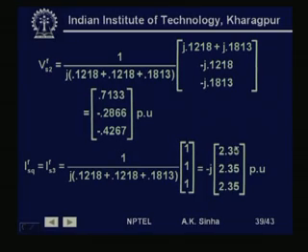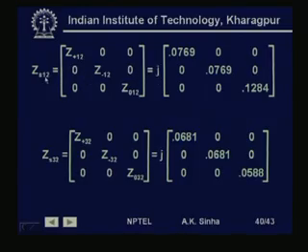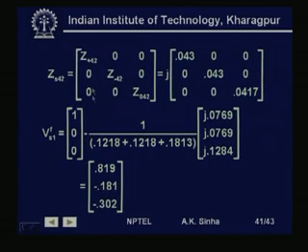So, we have got the values, I am sorry, this should be IFS2. So, this is the value that we will get for the fault current positive, negative, zero sequence. Now, we can transform it into the phase values. Similarly, if we want to calculate the currents flowing in different branches, we can use ZS12, ZS32 and all that for calculating the values at different branches.